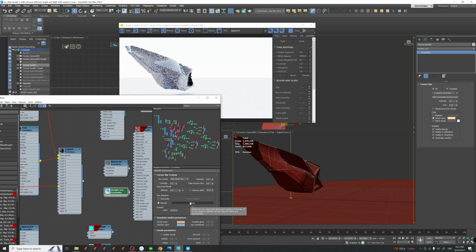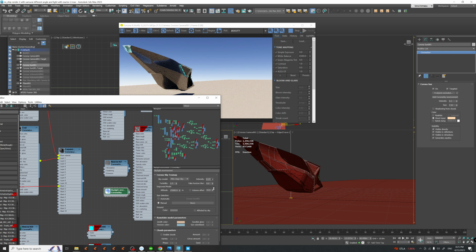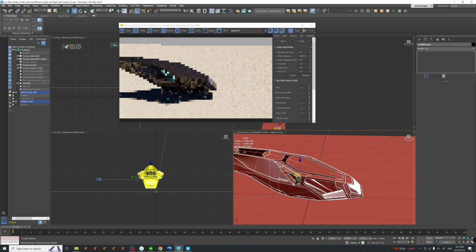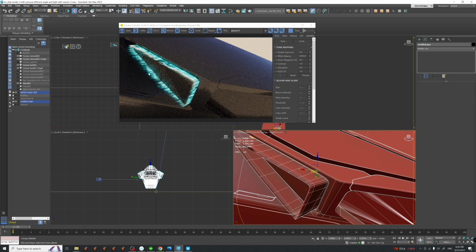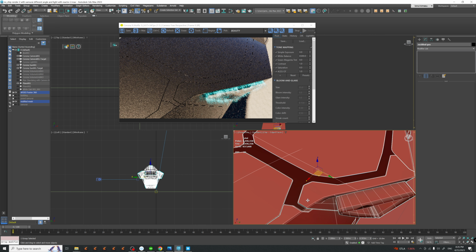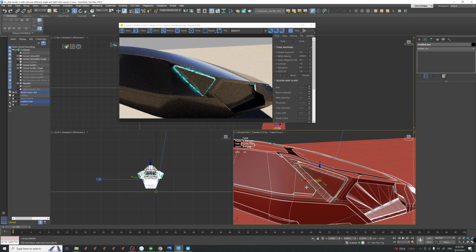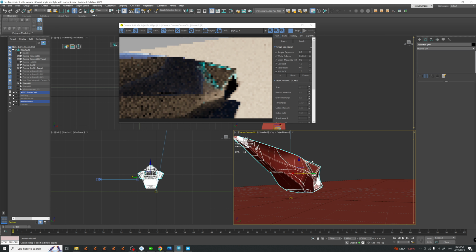Right, so I switch up to clear sky. Now, very interesting, if you set it up at 15,000 meters, you will have it a lot more towards blue. Now I'm adjusting the intensity so that I get a lot more blue out of it. Very important as well, and let me switch to perspective so we can see this. Very, very important. When I set up the sun, I set it up in such a way to exclude the plane that is giving me this effect. By the way, this effect is not done using particles, so it has its own drawbacks, but yeah, I didn't want to use any other add-ons and software for doing this effect. So for how it is at right now, I would say that is more than enough.